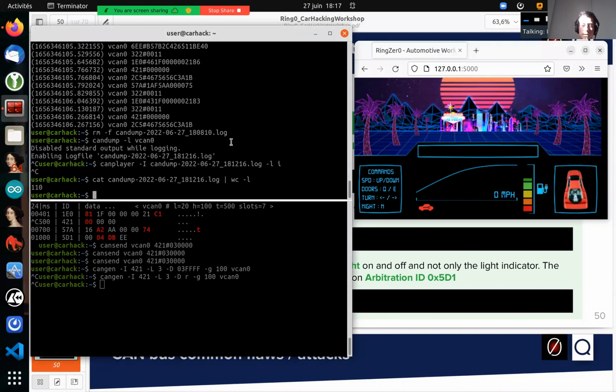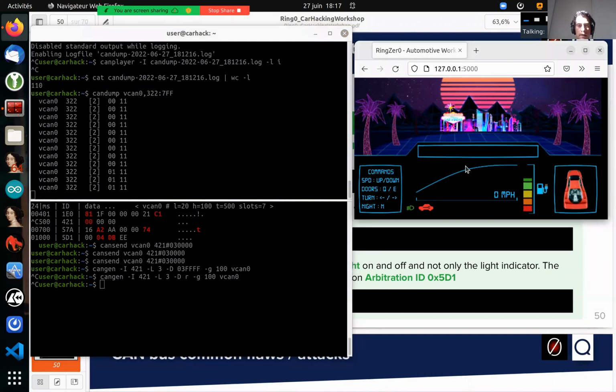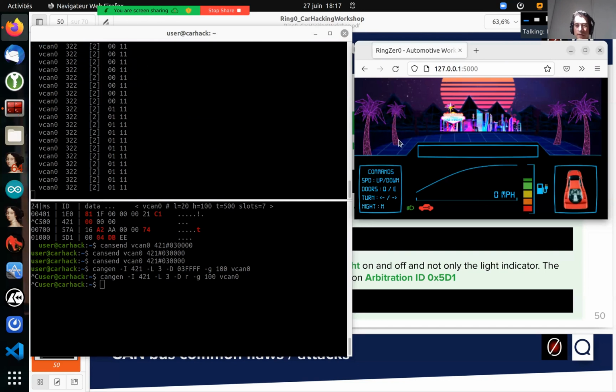It's using the arbitration ID. I will filter it right now. If I switch to night mode, the first byte switches, this is 0, but this is information. It just will trigger this one. If I, for example, do a CAN jam very quickly on 2 bytes, sending only 0, every 5 milliseconds, what's happening?